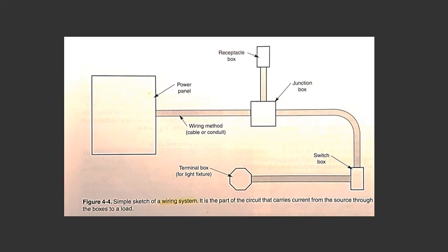Depending on the structure being wired, several different systems may be used. Regardless of the wiring system, it is important to have a continuous ground throughout the parts of the system in every circuit. Refer to Chapter 9, Grounding of this text. Grounding requirements. All of these systems are adequate for most installations. Again, refer to Chapter 9, Grounding of this text for grounding requirements. Some cannot be used where there are unusual hazards, such as extreme moisture, explosive gases, or corrosive chemicals.